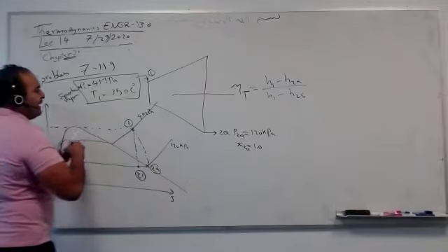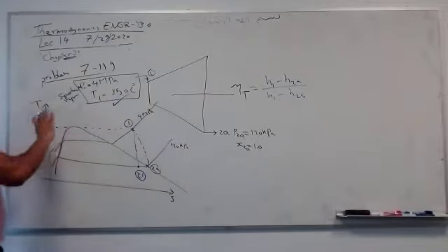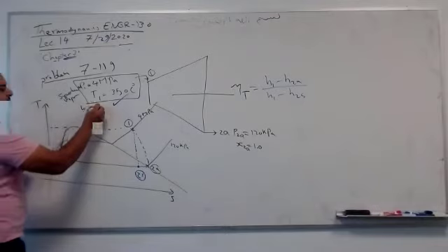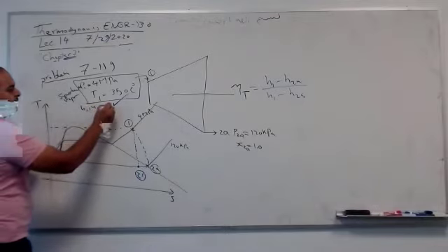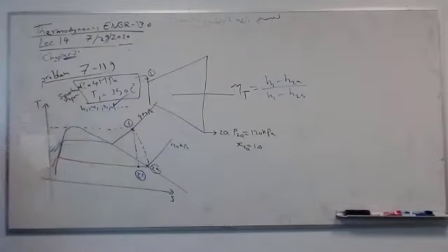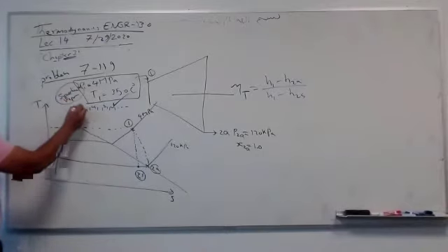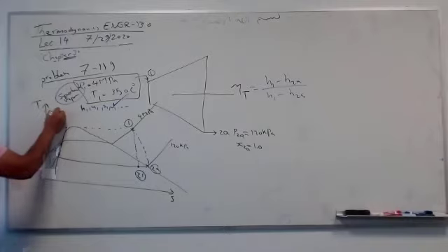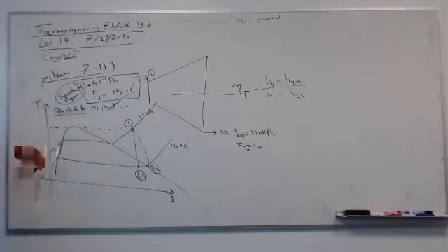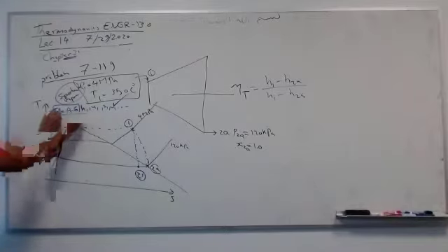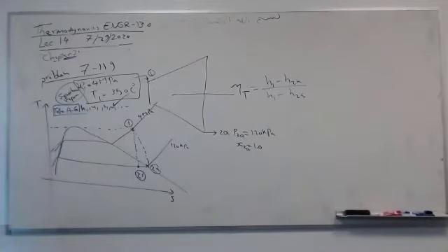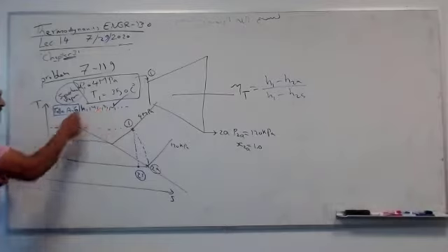So 1 is completely known. Superheated vapor, I can get everything: H1, U1, S1, V1, everything I can get from this. Guys, from which table? Table A6. Perfect. Table A6, go and get all the rest of the properties, including entropy now, something new.